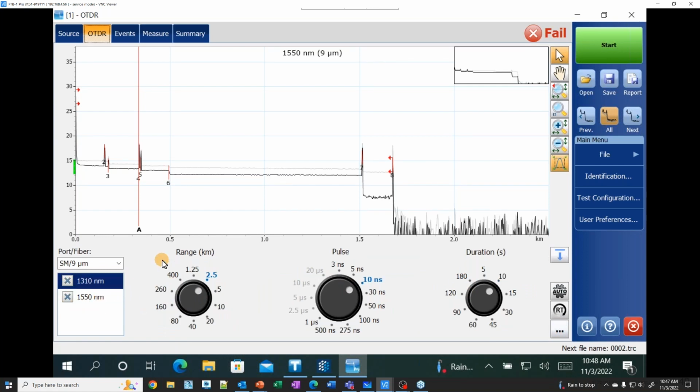But there's a lot of companies that are not doing 1310 anymore with high count fiber, because that's 50% more time. And at 30 seconds per fiber, per wavelength on an 864, that's over 24 hours, maybe 23 hours. So it takes longer to test than it does to splice an 864. So there's companies that are only doing 1550, knowing that if 1550 is good, then 1310 is good, right? And 1550 will see more issues than 1310 will in most situations.